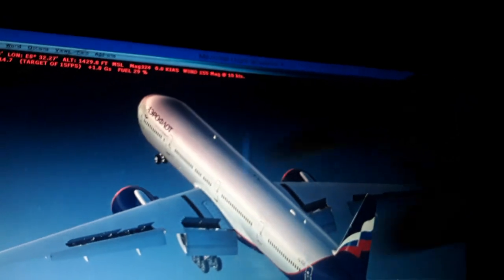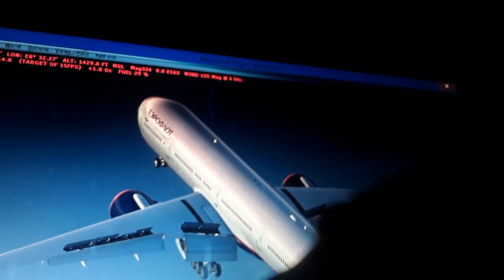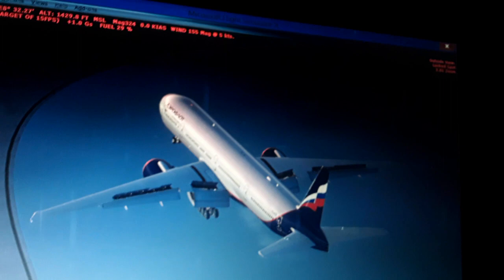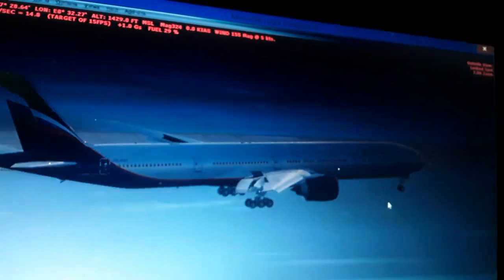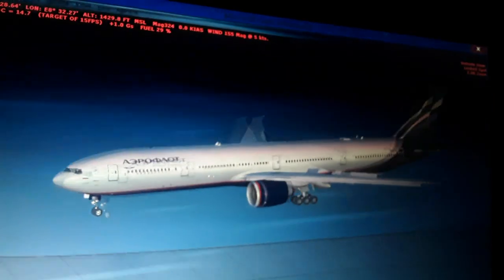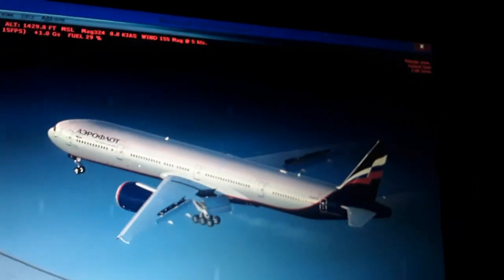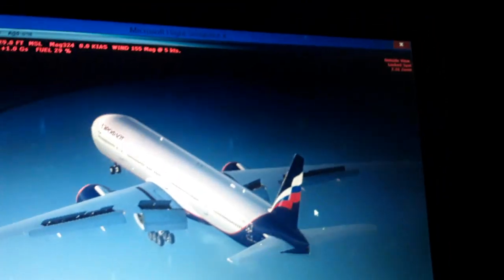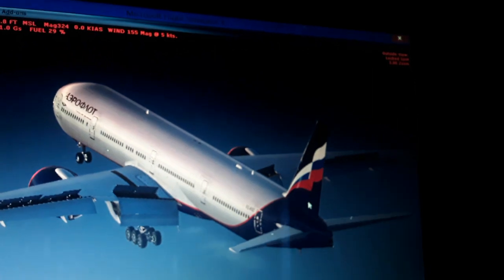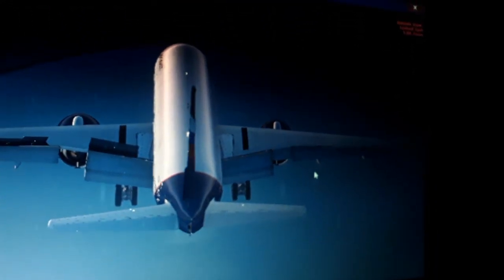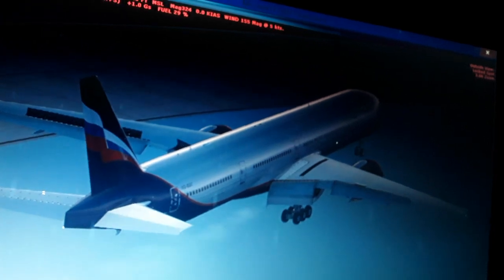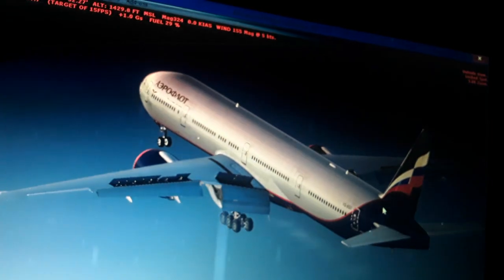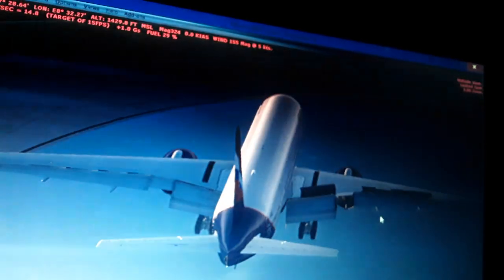So we have more vectors. You can see the left and the right wing, and the engines to propel the aircraft forward. We can only propel it, move it forward, and not make it climb. We need the lift from the wings. We have other forces also applied. We have the moment arm and the lever arm from the tail, from the horizontal tail and the vertical tail, that make the aircraft climb up and descend. Also bank roll left and bank roll right.